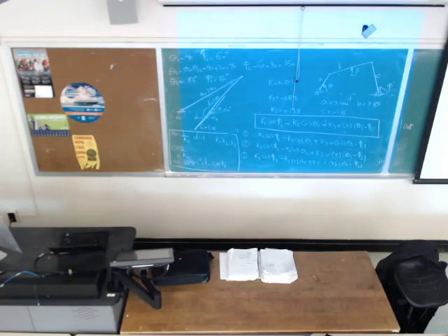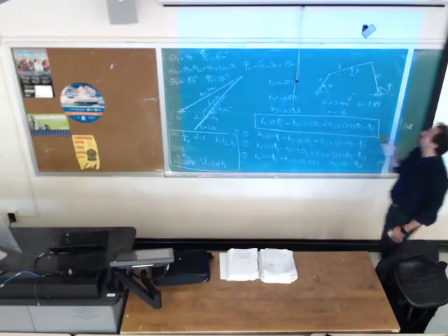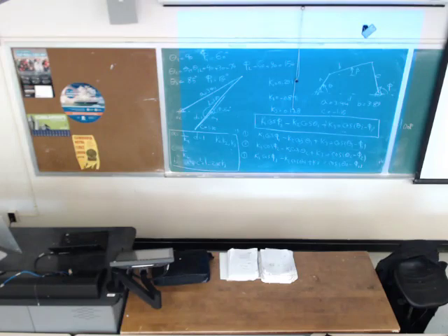And if I ask you to draw the mechanism in the second precision point, we move the first link, the second link, by the angle of theta 1,2, which is 30 degrees. It's going to rotate by 30 degrees. This link is going to move in this direction. And the angle, P12, is 90. So this link is going to rotate by 90 degrees. It's going to end up here. That's the second precision point, and the third precision point is going to be the red one. The output link is located at 180 degrees.